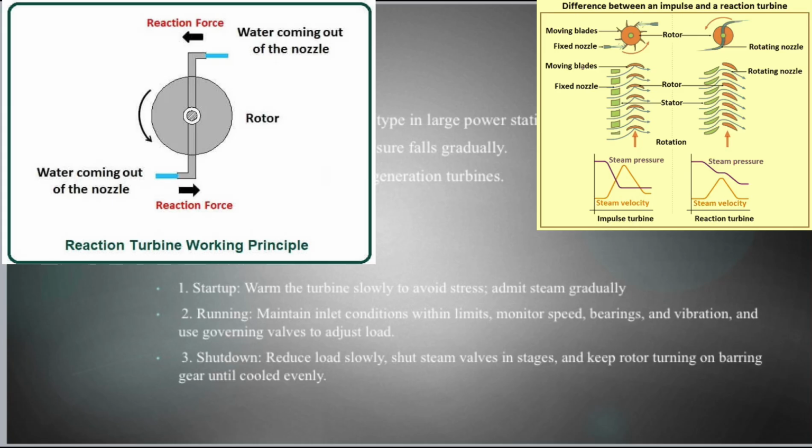Second is the running: maintain inlet conditions within limits, monitor the speed, bearings, and vibration, and use governing valves to adjust loads.